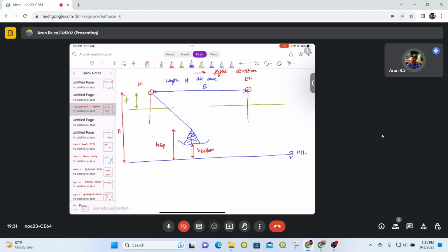In your second exposure, it will be to the left of the principal plane. So this is the point capital A, this is the point small a on the first photograph. This is your small a on the second photograph. This is at a distance of x1 from the principal plane, and this is at a distance of x2 from the principal plane.